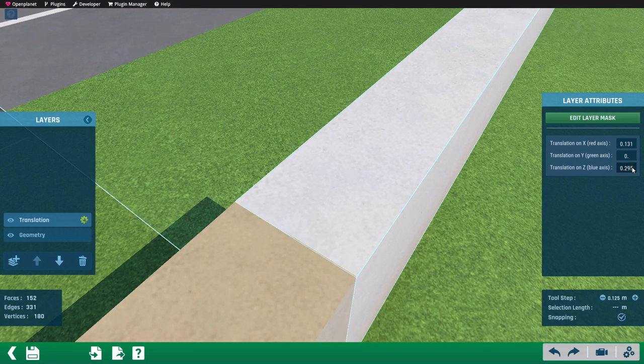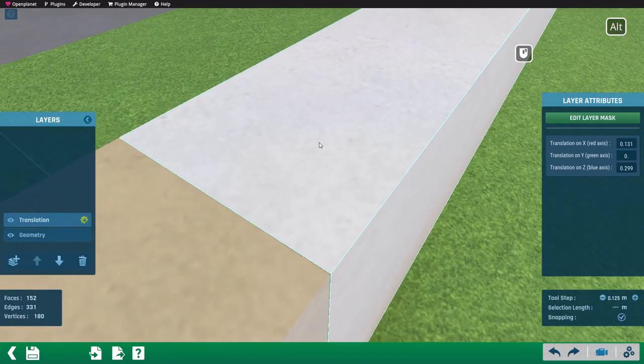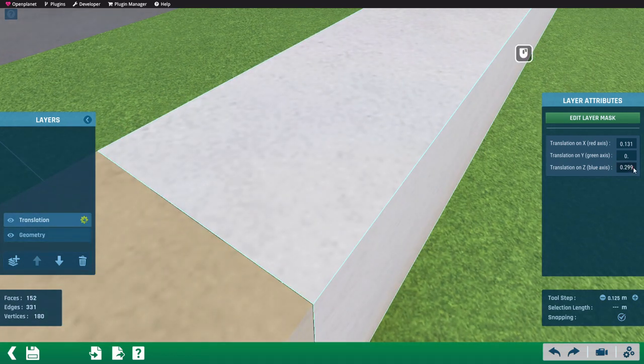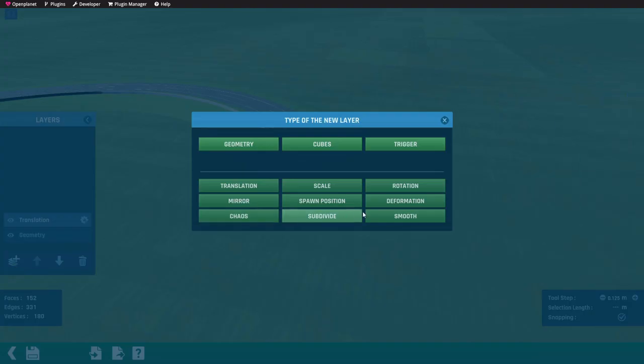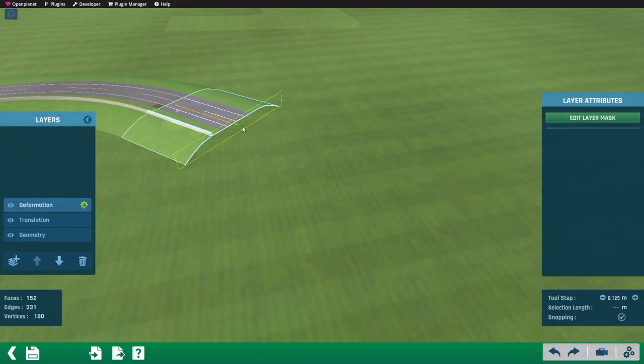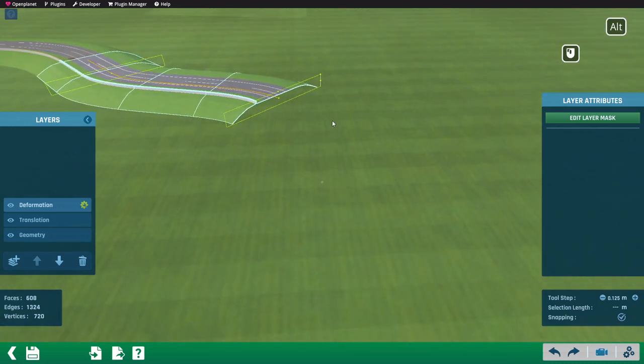Applying modifying layers like scaling or rotation is more complex if not impossible if you want to maintain a coherent racetrack. Care must be taken to ensure understandable orientations of the spline to be able to cleanly place new items at the end of the previous one, limiting wild combinations of bankings, slopes, and non-right angle turns. Like the results of the first method, these items are also likely not reusable for different tracks unless you want to copy complete sections.